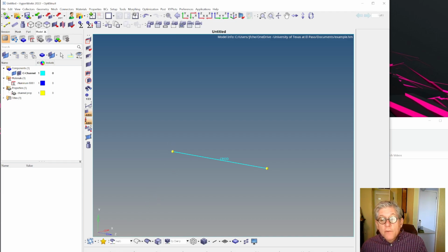So if I go here under geometry, temp nodes, and then clear all, or you can select them, but I'm going to clear all. They go away. Now there actually is a node still here and here. It's the actual Nastran grid point, okay? All right, so now we're going to create the constraint. We're going to fix this point here at all 6 degrees of freedom.